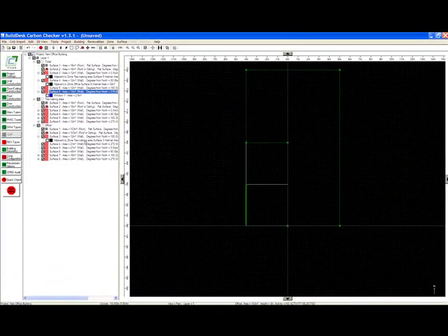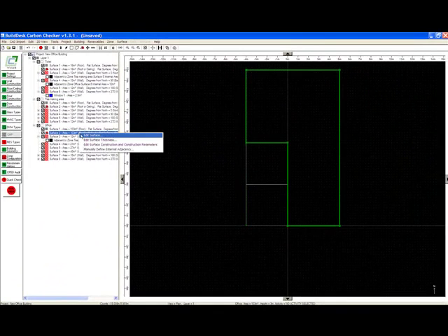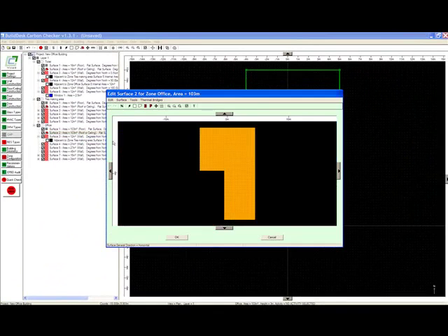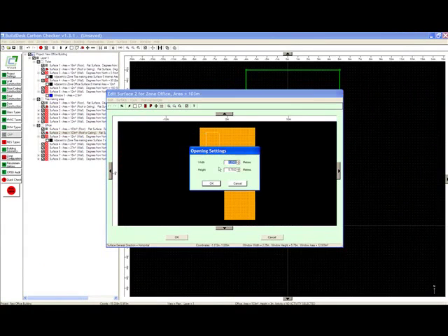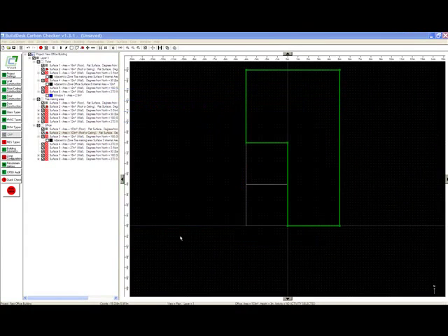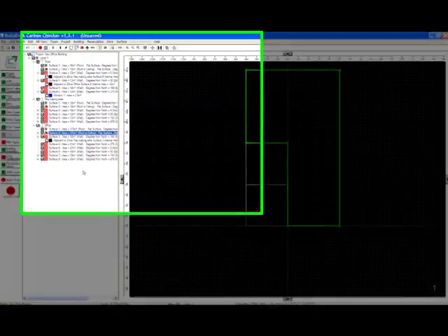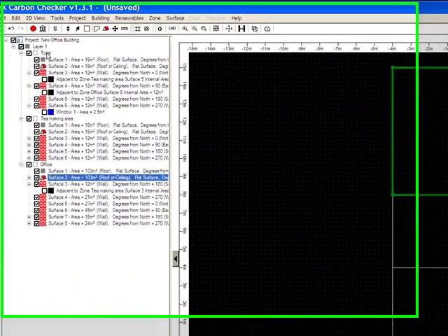You can also add skylights, so let's put a skylight into the office area. Again, we edit the surface, choose the window tool and drag and click OK when we're happy with the size. We now need to complete the zone configuration by putting the zone activity in for each zone.